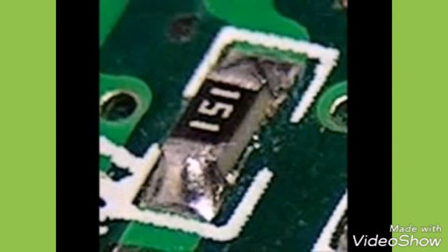This tiny surface mount resistor has 100 printed on it. It uses the same coding system as color codes. This one is 10 with 0 zeros after it, or just 10 ohms. This surface mount resistor has 151 printed on it. That would be 15 multiplied by 10 raised to the 1 power, or 15 times 10. In other words, 15 with 1 zero after it, 150 ohms.